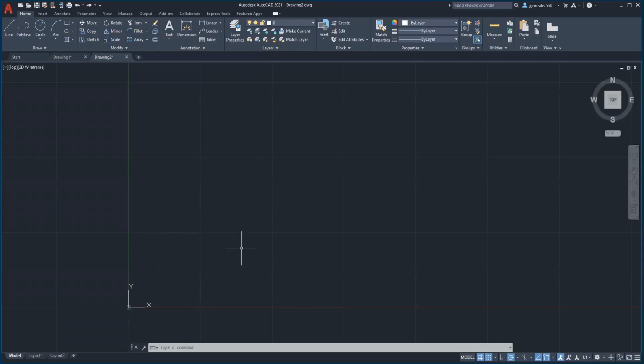Where was the button to put in the exact point? Oh, so you can not have to aim, that is the snap mode. See, let me show you the difference, right? So if I have snap on, it kind of centers itself, right? But if I turn it off, I'm just freehanding it and I gotta eyeball the center, which is probably not gonna happen, right? So make sure it's on, at least for now. Most of the time you'll be using it, and then you can also customize snap to snap certain ways or certain spots, etc.